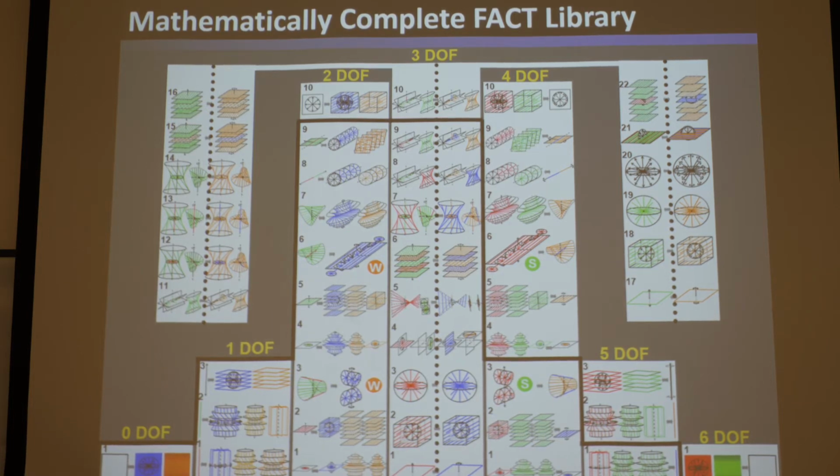But again, we don't really use orange wrenches or black moments. We really only synthesize flexures and compliant elements that have pure force wrenches in them, the blue lines. Of course, one blue line is a wire, a plane of blue lines is a blade. And all the ways we generated parallel elements, they were all just filled with blue lines, okay?